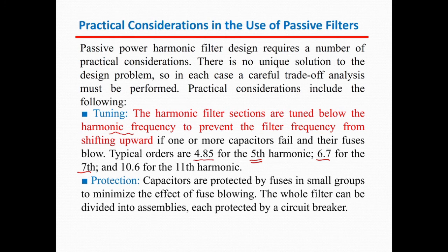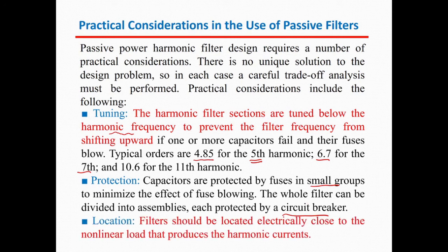Protection. Capacitors are protected by fuses. Okay, and they are placed in small groups to minimize the effect of fuse blowing. The whole filter can be divided into assemblies, each protected by a circuit breaker. Location.